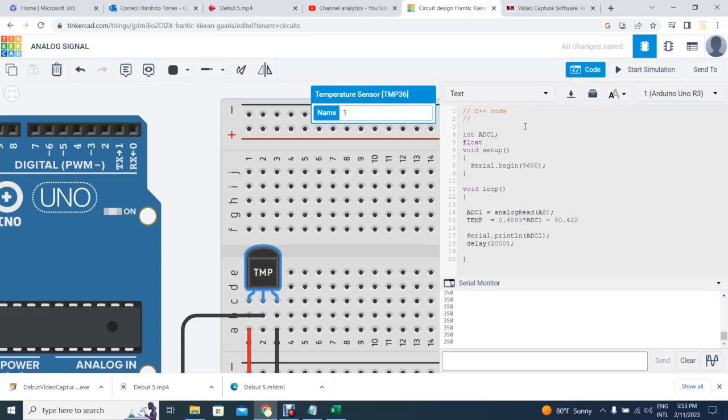Again, if you are using caps, it is caps. It is case sensitive, so you want to be careful here. So it's temp because the name here is temp. Now, the variable temp will be the equivalent with engineering units. So whatever is being read by the ADC1 is going to be converted by this equation back to what we want, which is temperature. Now, at the time of printing, let's fix this. I'm going to be printing first the ADC value. We wanted this to look good, so let's fix the printing process better. Let's say serial print, and we're going to print here a little text.